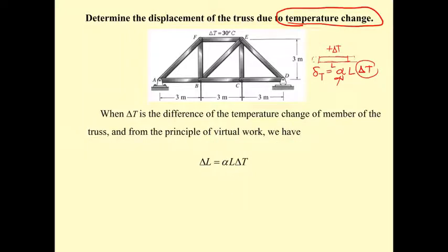Okay, and what we have is what? When this one expands due to the heat, point E and point F won't like it to expand. It won't allow it to expand. When it won't allow it to expand, what happens is this member will be subjected to this force. And by Newton's third law, this is going to push this guy like this.